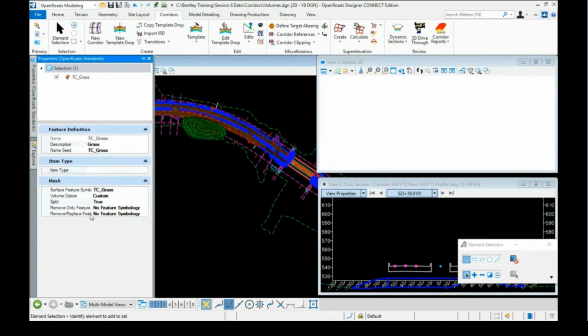This is going to be moisture density control where you're removing a certain amount of existing ground underneath. And so what this does is it allows you to split what's above and what's below the existing ground when you quantify it there. So it's kind of a subtype of a design type volume option, but it allows you to do this split above and below existing ground, what gets removed and what gets replaced. Okay, so we'll set grass back like it was as design.